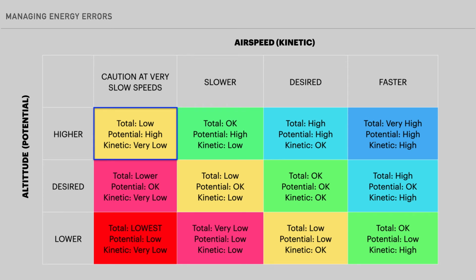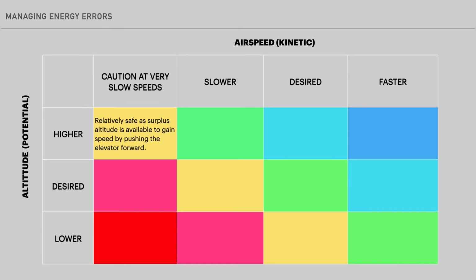On the other extreme, this problem can be compared to an approach to stall at safe altitude. The low airspeed represents a high angle of attack and thus very high drag. By reducing the angle of attack, the pilot can significantly decrease the induced drag and thus increase airspeed. We can then trade the excess altitude for airspeed. The appropriate response then is to apply forward pressure on the elevator control, reduce the angle of attack, and gain airspeed at the expense of altitude. Upon reaching the new desired energy state, adjust pitch attitude and throttle setting as needed to maintain the new path speed profile.